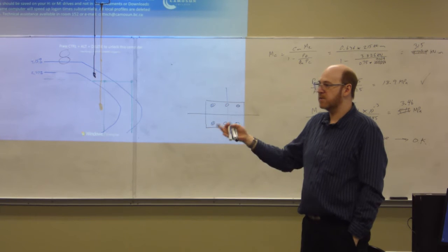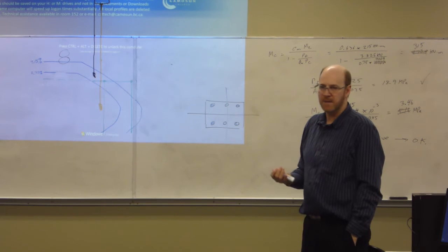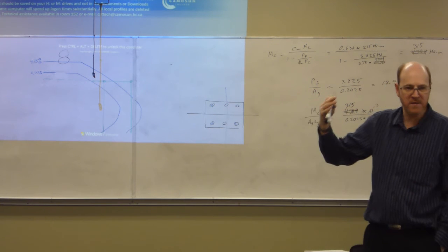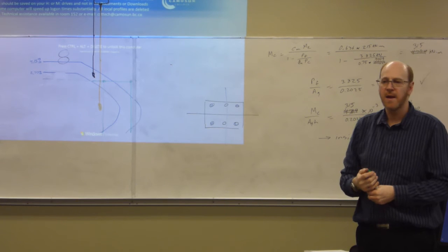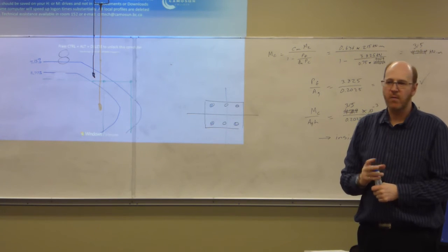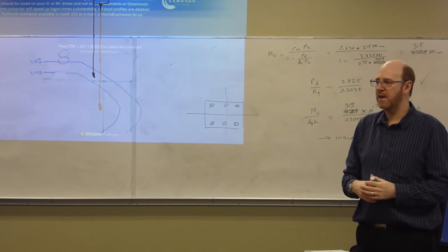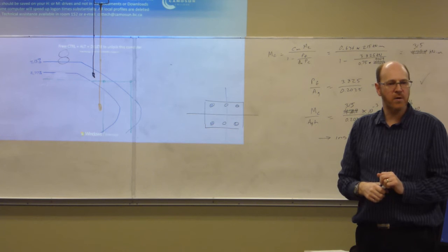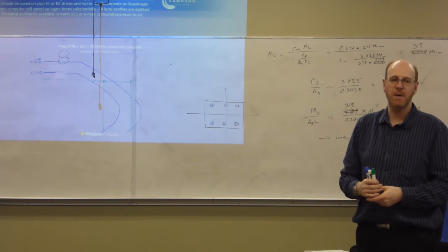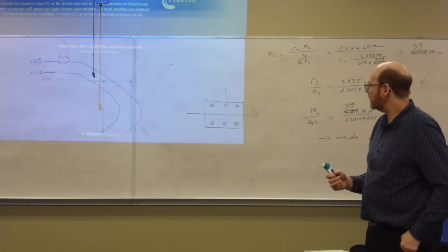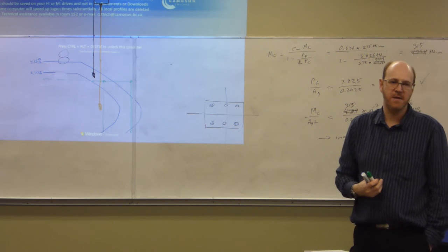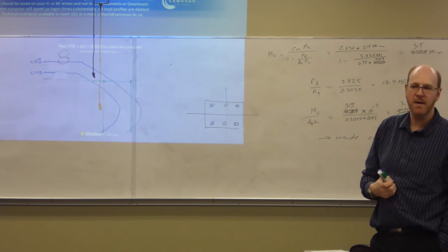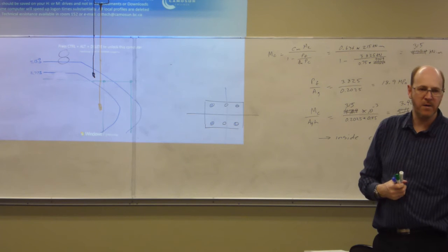So what we did in class in terms of figuring out what the moment resistance is and designing the beams is perfectly fine. This sort of process and what we were talking about last week with the slabs and coming up with that pattern of reinforcing and so on is actually more of a drafting exercise. Right? We've got some basic parameters that I want to work within, and now I want to just sort of tweak the spacing and the parameters a little bit in order to come up with a configuration that works and is reasonably efficient. It is possible to spend an awful lot of time going through this process to optimize rebar and minimize the amount of wastage and come up with a system that's reasonably economical.